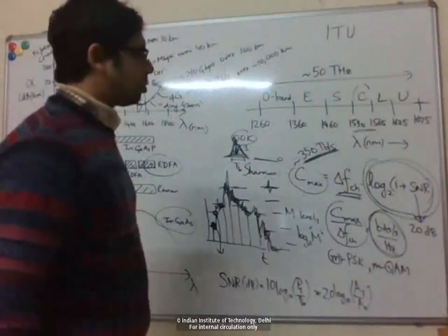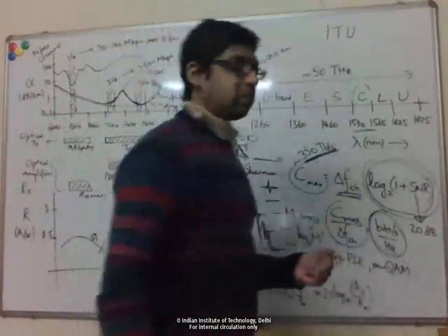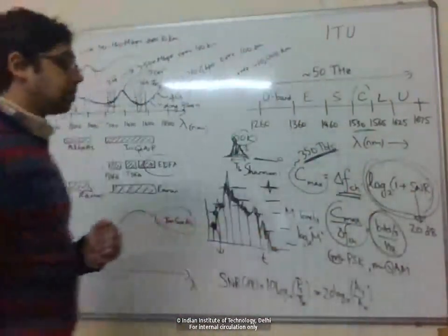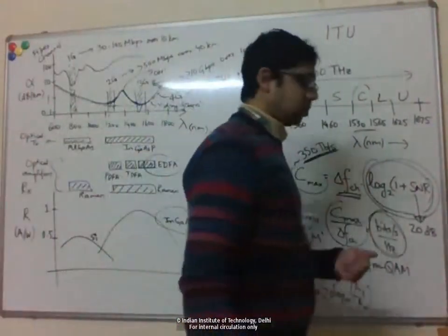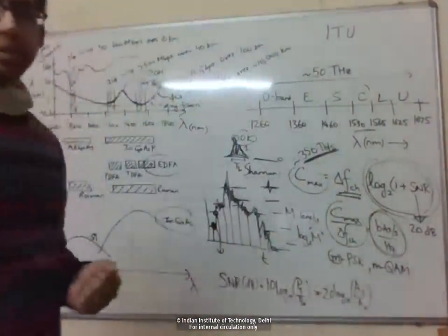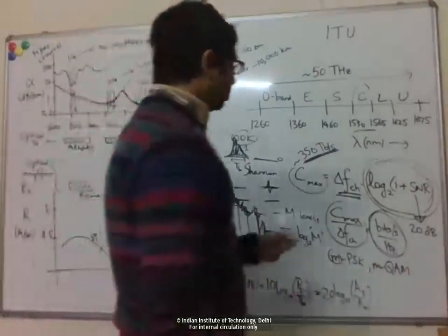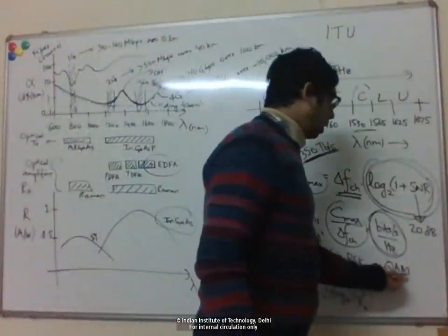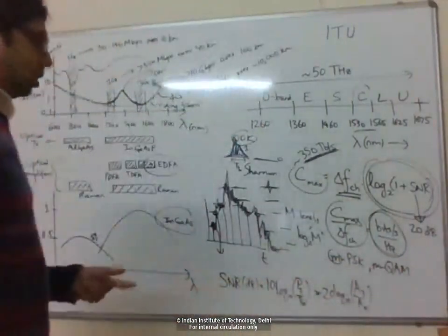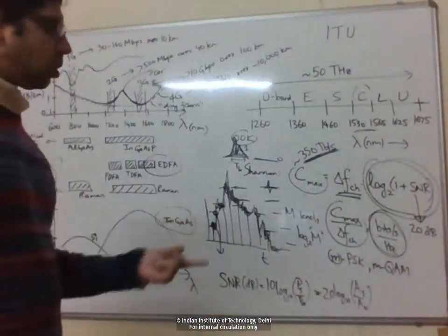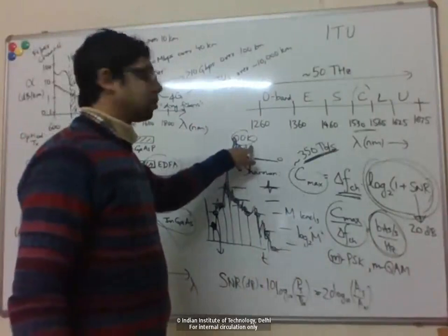If you look at the state-of-the-art modern day communication systems, they are utilizing some sort of coherent modulation scheme to take advantage of this SNR. Optical systems, for example, are using 16 QAM or even higher sometimes. But you'll see in the course, these modulation techniques are more complicated. They require more complicated transmitters, and also more complicated detection, whereas this one is very simple in terms of detection.